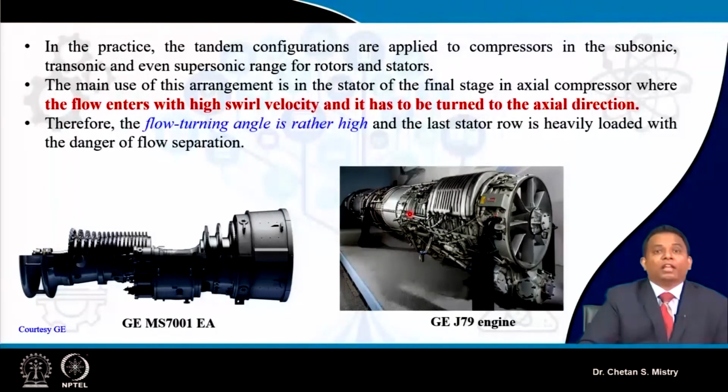Mainly at the end of the HP compressor, at the entry of your combustion chamber, your flow will have high swirl, and you need to transfer your air to the combustion chamber in axial direction. That's where the blade turning requirement by that stator is very high, and there are more chances for the flow to separate in that particular region.